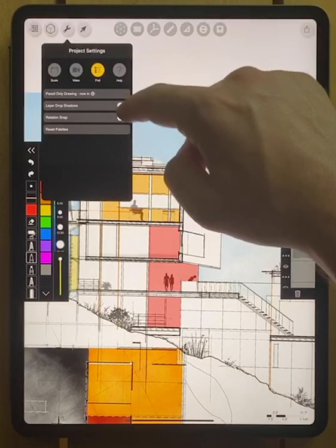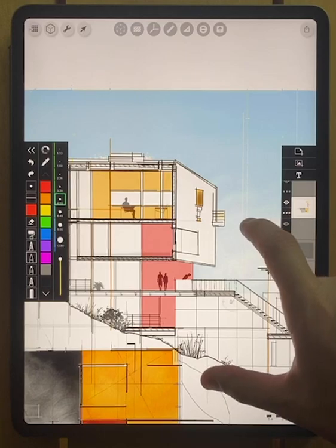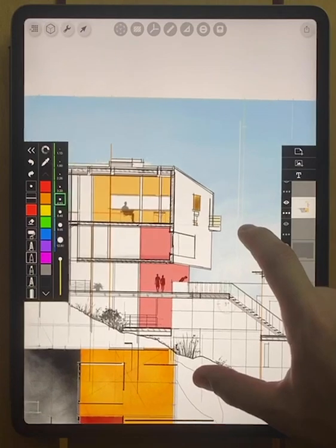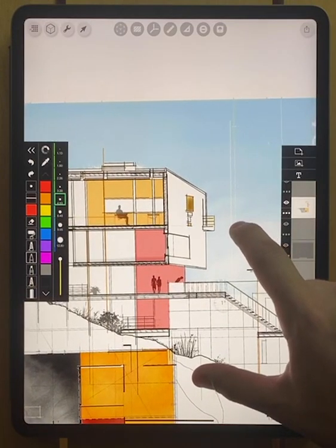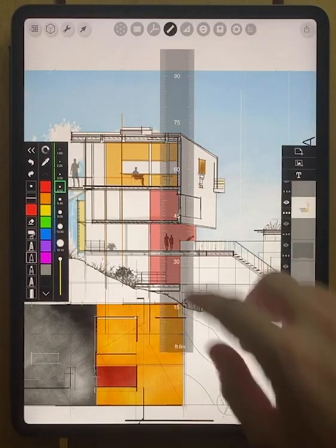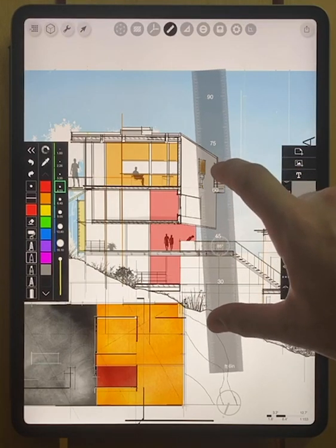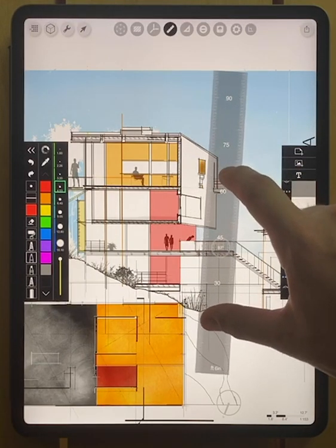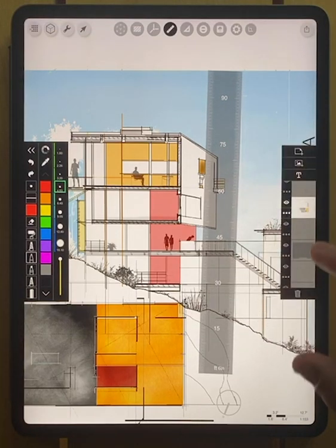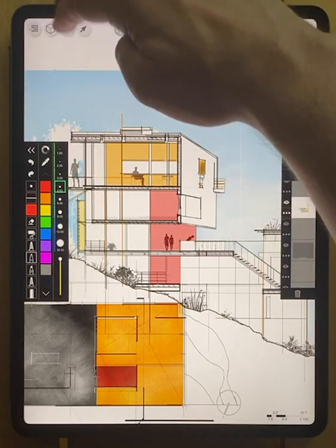Another trick though with this, if you do have rotation snap turned on and you are getting snap to 0, if you rotate 3 times, then suddenly you have full functionality, full ability to rotate to those fine degrees of 1 and 2 degrees. This also works for our tools if we're rotating the ruler and we want to get beyond the 90 or beyond the 0 degree. If we rotate it back and forth 3 times, now you can see I'm getting 88, 89, and I can set those much more fine angles than we would be able to.